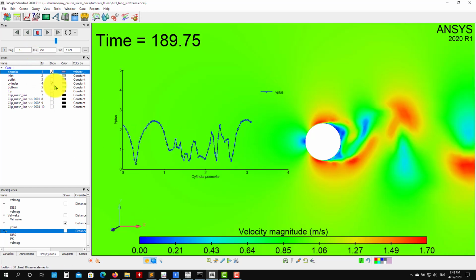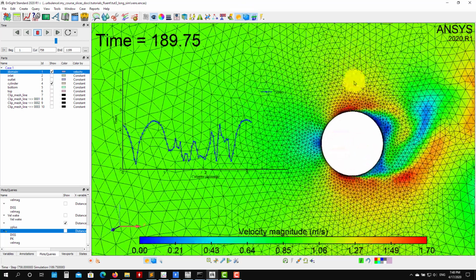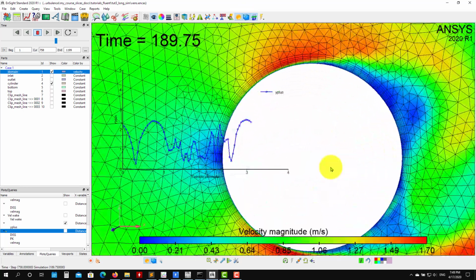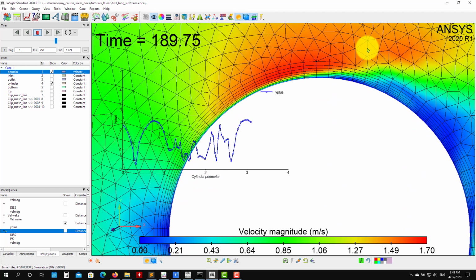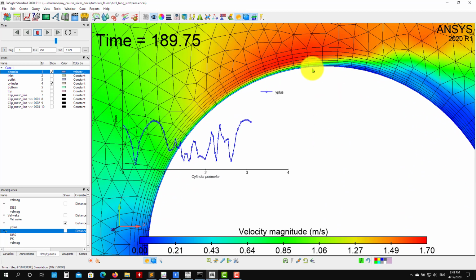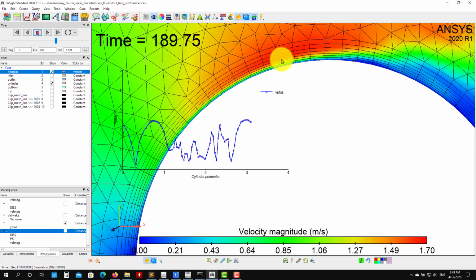And we can also plot the mesh. So look at our mesh. Probably it would be better to add more inflation layers. Here I think we have 8, but probably more would be better, and make it finer close to the surface to be closer to 1.